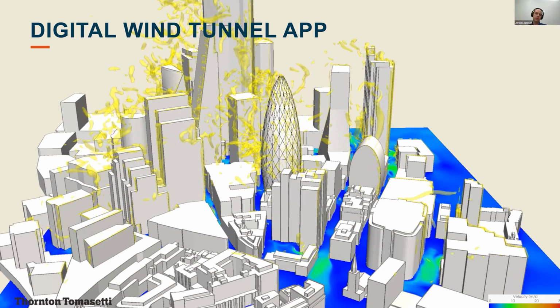You need to set basically the size of a domain and your coarseness of a mesh and sort of things. But actually, you can automate a lot of that, because that's kind of governed by the tallest building, whether it's the building you're looking at or the surrounding buildings. The wind speed that comes in, typically we run it at 10 meters per second, 10 meter height. The wind speed varies over height, so it's a logarithmic relationship, which is based on that terrain roughness, which is the first input. So again, if you automate that, you can take that away.